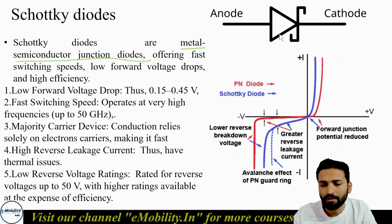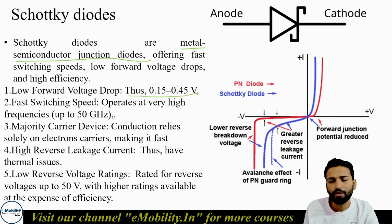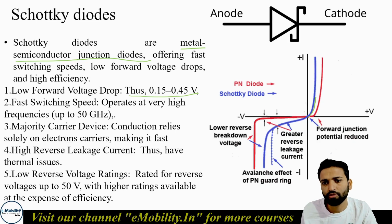So a Schottky diode consists of a semiconductor plus a metal. Both are combined, and this gives rise to the very low cut-in voltage. Cut-in voltage is when the current flow starts, at the voltage where the forward bias is actually working. These are also used in very high switching, like 50 gigahertz switching, and the majority carrier relies mostly on the electron, and that's why it is very fast.